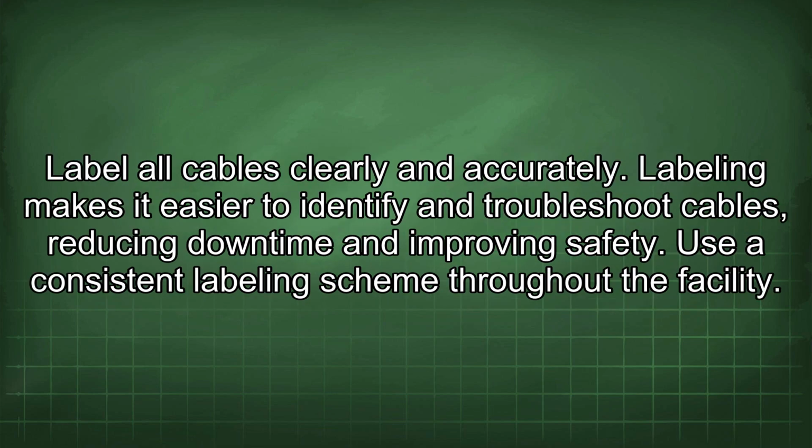Label all cables clearly and accurately. Labeling makes it easier to identify and troubleshoot cables, reducing downtime and improving safety. Use a consistent labeling scheme throughout the facility.